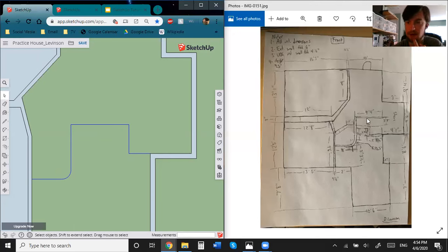Did I do that right? Yeah, that's fine. Doesn't have to be perfect. Offset tool, click here, and we're going to go upward. You know, I'm actually going to change something. I'm going to not have this line here selected. So this one, that arc. I don't think it's working. There we go. That line, that line, that line. I'm going to leave this one out. And then offset upward, I'm going to do this 4.5 inches.